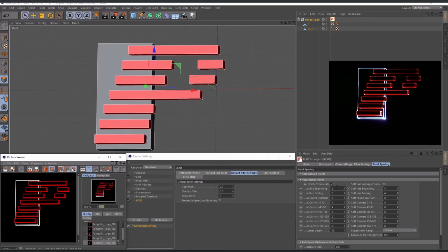The next filter lets you adjust how many points will be added at the beginning of a visible line and also at the end of a visible line. In general, the default value is already set to a quite balanced number. But in case I would like to sharpen the corner points of my graphic, I may change this. So I will disable the acceleration function, but increase the number of beginning and end points, and thus I can also achieve sharper edges of my graphic.